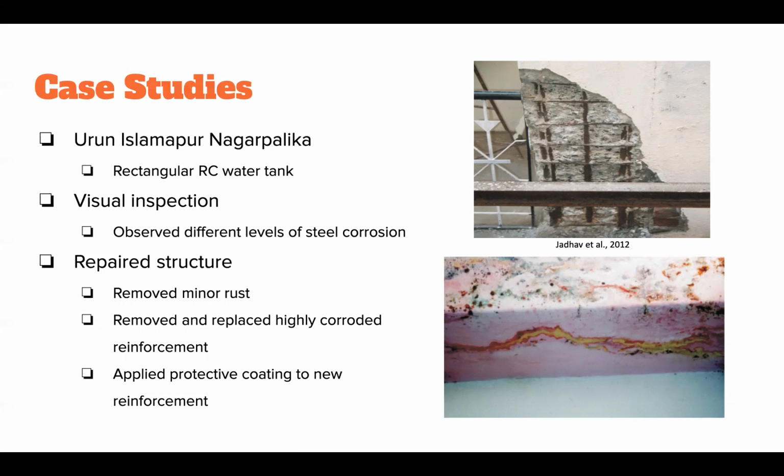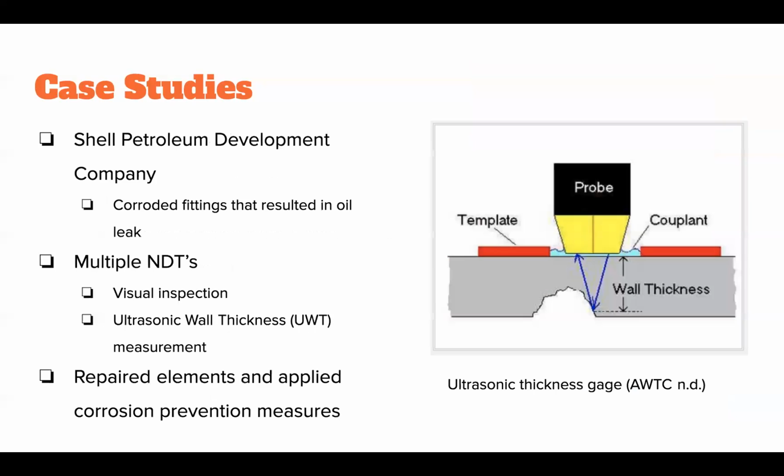Visual inspection determined repairs were needed. Highly corroded reinforcement was removed and replaced with a protective coating that was then applied to the new reinforcement.